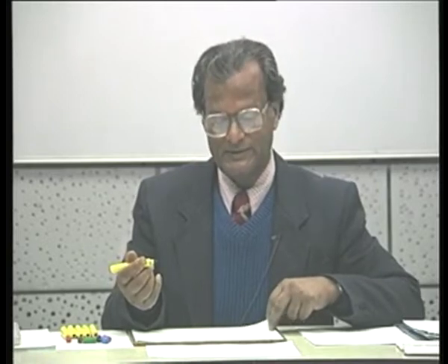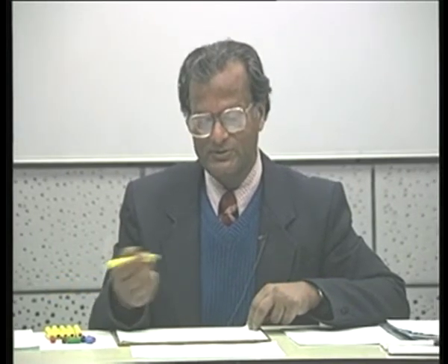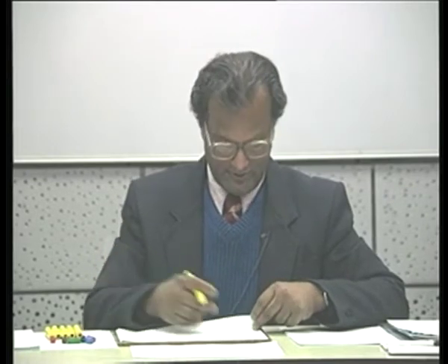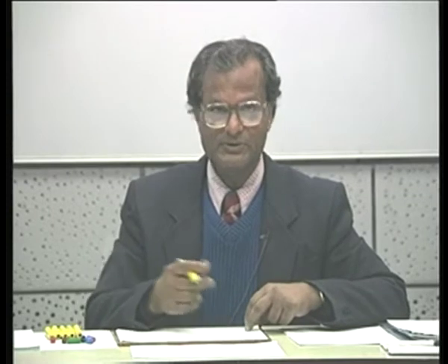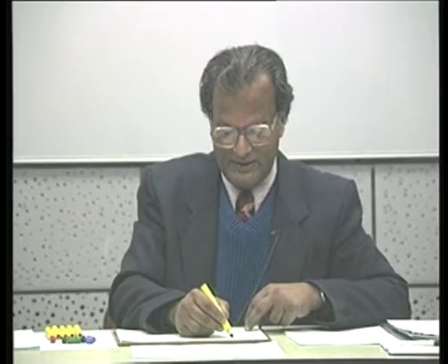That means transfer functions of the type that is obtained with double tuned circuits can also be obtained otherwise. One of the examples I gave was electrostatic coupling through a capacitor. It could also be a resistive coupling. It could also be some other kind of coupling which we shall discuss at the end of this class. Now, the example that we had taken was